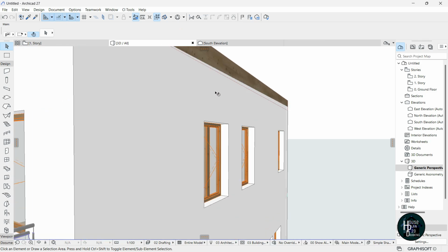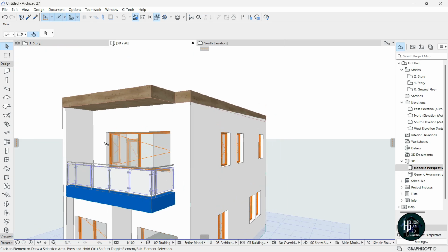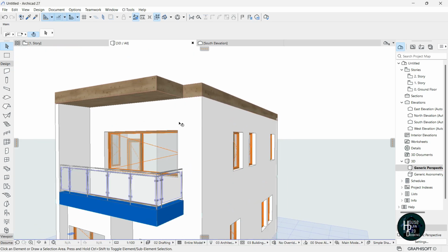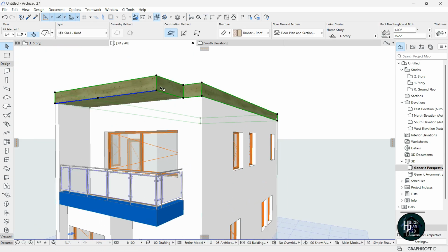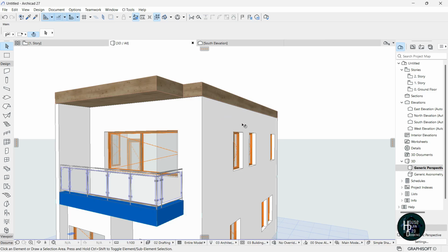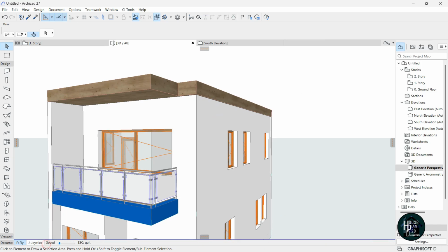If you look properly at this side here, it tilts. I know that the angle still tilts downwards like that. For this particular drawing, I don't want it to tilt. Okay, so what I'm going to do is I'm going to just click on this roof itself, and I'm going to click on this icon here and change it to be the percentage. Okay, I like this and change it to be 0. Click enter, and that's gonna be perfect like so. Okay, so that's very important you guys do that.